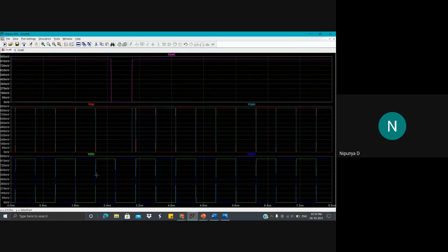But when you see it with respect to bitline and the Q, it should have been the same. But there is some sort of glitch which we can observe here. In order to analyze why this glitch arose, we need to know what is happening with respect to the word line. I did mention while explaining that whenever the word line is kept high, that time you will be able to read or write, whereas when it is logic low or zero, it will be in hold state. If you carefully observe here, it is dropping from high to low. That means for a short period, within this range, it is in the hold state.